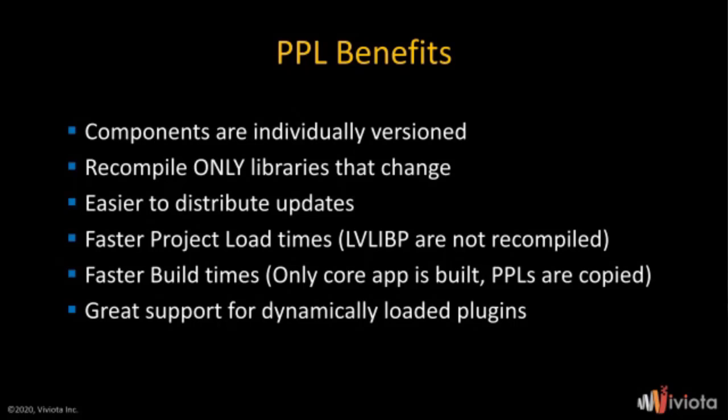And then the other piece was much more tied to the fact that they're dynamically loaded. The question was around the idea that PPLs get essentially unloaded from memory when they're not used. So this is some linkage stuff that I think gets pretty unique. Yes and no. You can create an architecture that loads PPLs and unloads them when they're done. There are some intricacies to that. Typically, when you bring a library and a class into memory, LabVIEW leaves it in memory until the application is done, or until the caller is out of memory.